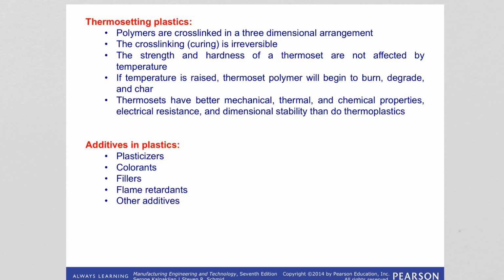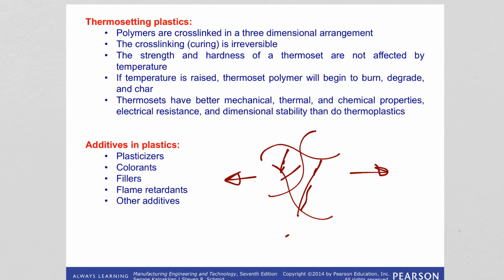Thermosets are where there is cross-linking, carbon bonds, strong bonds between the chains. Of course, this prevents chains from rearranging during the deformation, right? When we stretch, they cannot align like this. The thermosets cannot therefore flow easily over each other. So this of course gives them strength, but this process is also called curing, which is irreversible. So these materials cannot be recycled, unfortunately, and many polymers used in composites are thermosets, and therefore it is difficult to recycle.